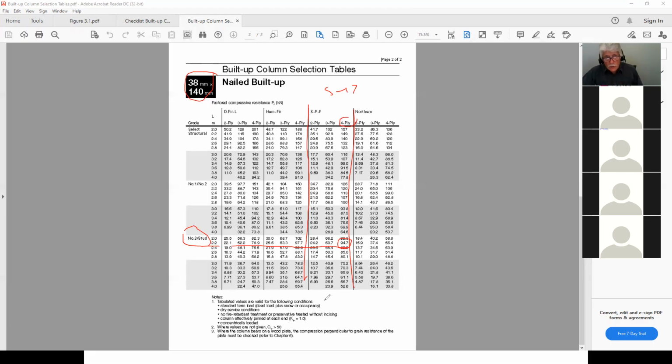Okay, and there's my answer. I'm pretty sure if I wouldn't have used a live load reduction factor, I probably couldn't find a value of Pr, because it would probably have been higher than 91. So you're allowed to do that, as long as your area exceeds 400 square meters, I mean, approximately 400 square feet, 20 square meters. I shouldn't even talk in square feet, because that's me, old school.